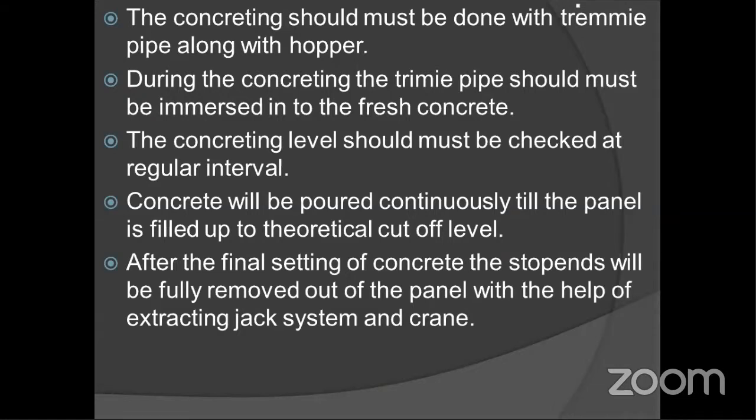The main thing is, while doing the D-wall fabrication and all, if we have to install the inclinometer, we have to put one hollow pipe throughout the cage at certain decided areas, and based on that only we will get the deflections.